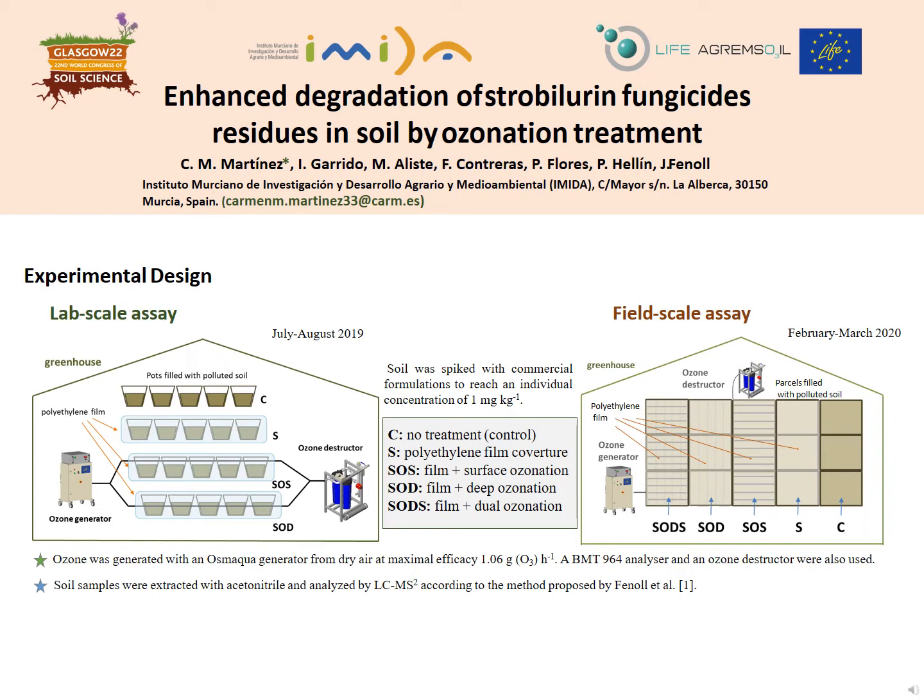Experiments at field scale were performed in a greenhouse equipped with 15 parcels. After filling the parcels with the soil previously contaminated, 5 different treatments were conducted during 50 days. The 4 explained before, and a 5th one, the SODS treatment, where soil was covered and ozone was simultaneously applied at surface and at depth. The film cover was impermeable to ozone, acting as a gas barrier and avoiding possible fluxes of this gas to the atmosphere.